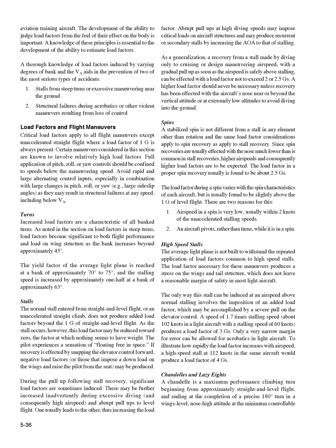A stabilized spin is not different from a stall in any element other than rotation, and the same load factor considerations apply to spin recovery as apply to stall recovery. Since spin recoveries are usually effected with the nose much lower than is common in stall recoveries, higher airspeeds and consequently higher load factors are to be expected. The load factor in a proper spin recovery usually is found to be about 2.5 Gs.